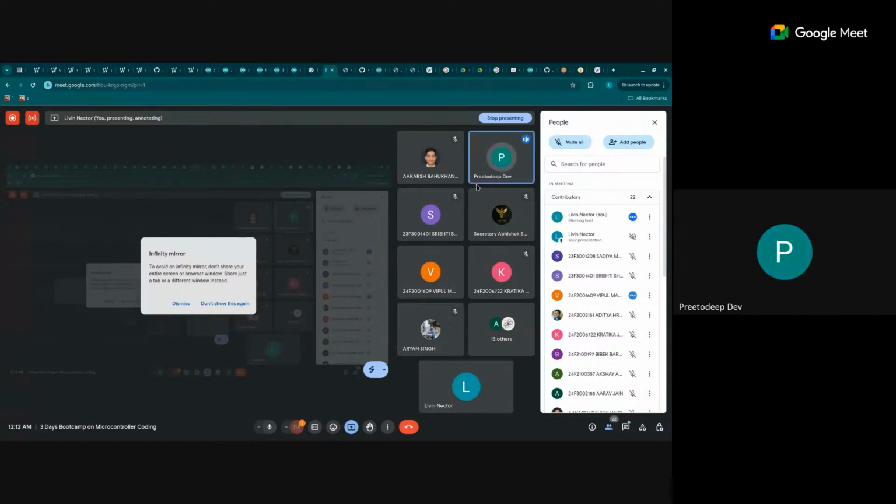Sir, for other devices that have programmable GPIO pins, let's say if I want to do something on my Pi, would the code be similar? Would I be able to use the same Arduino language and would it run on any other programmable GPIO interface? The Arduino framework can be used for other boards also, the STM boards and others, but that requires an additional library.